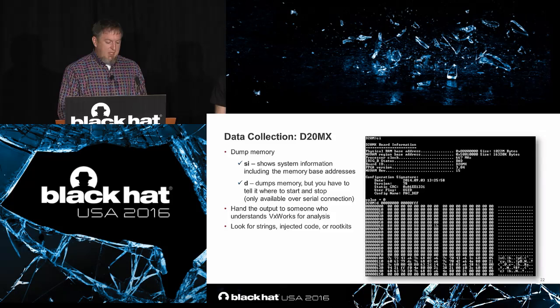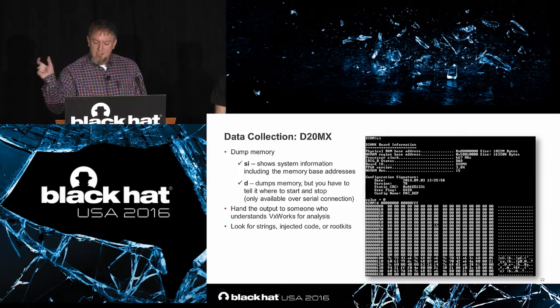So that's really great. You can show the sensitive information, shows where the NVRAM starts, and that's what you want to look at, and the physical RAM, and it shows the addresses where you start to dump them. So I show in the command there D, and I start with the address 00, and I go to FFF, and then it just starts dumping it on the screen.